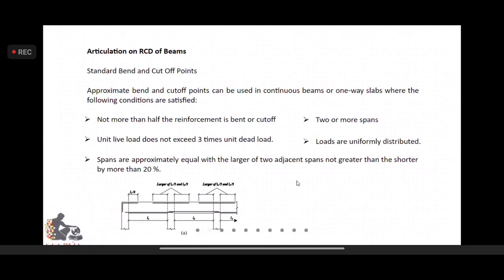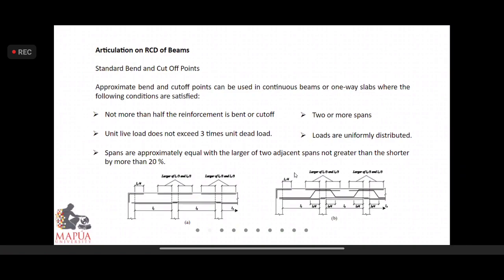And then, we consider this one as well. Malapit na tayo. Okay? Diretso na. So, please take note of the splice recommended requirement, splice length. The area wherein you're going to set your splicing, yung pagdudugtong, hindi dinudugtong basta-basta yan. May mga corresponding areas yan.